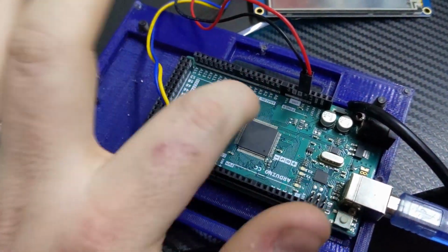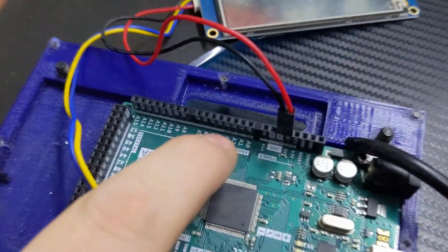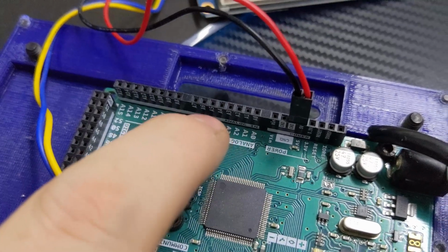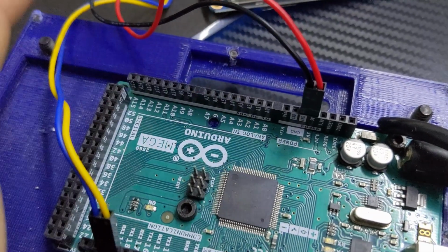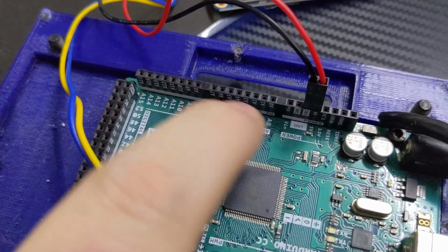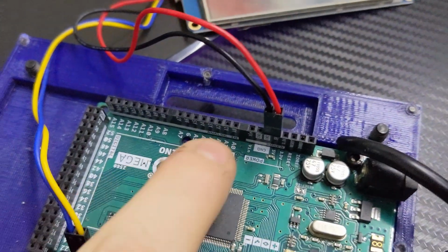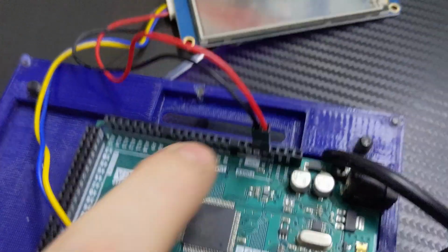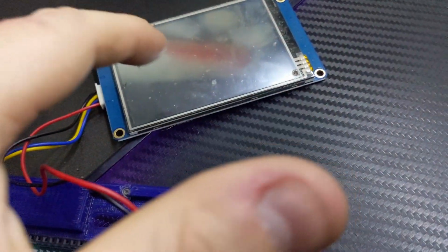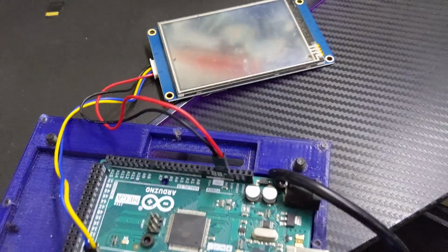So let's confirm that our plasma input voltage works. So let's set up a cheater circuit. I'll show you a quick way to do it with a small potentiometer that allows me to adjust my input voltage here between 0 and 5 volts, and that'll allow me to mimic a plasma cutter, and so we can do some testing. So let's get that going.